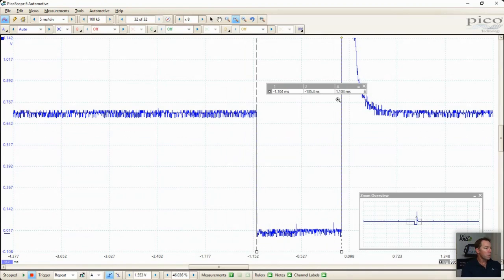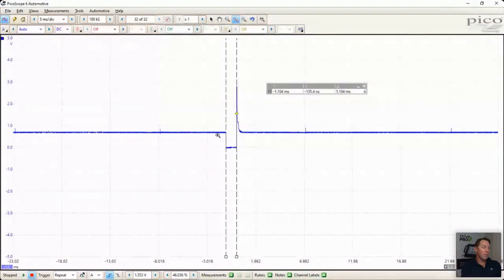It's a bit unrealistic. Most fuel injectors on cars we see are open around, at idle, around 4 milliseconds. And then when we bring the RPMs up, we actually see this time-based change. So what this is handy for is doing comparison between injectors. We might have an injector that's a little bit lazy. We might find all the drivers a bit lazy. We might find that we've got a cylinder running a little bit rich.